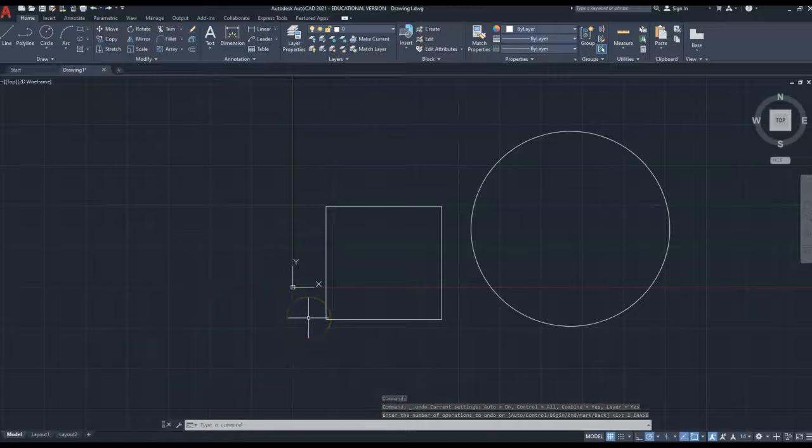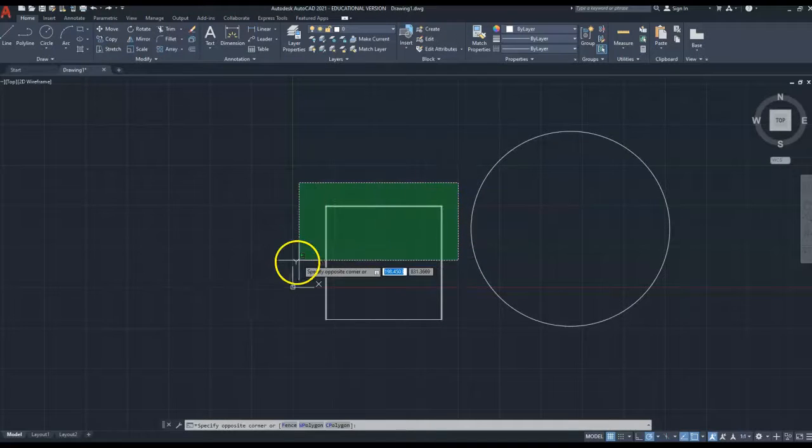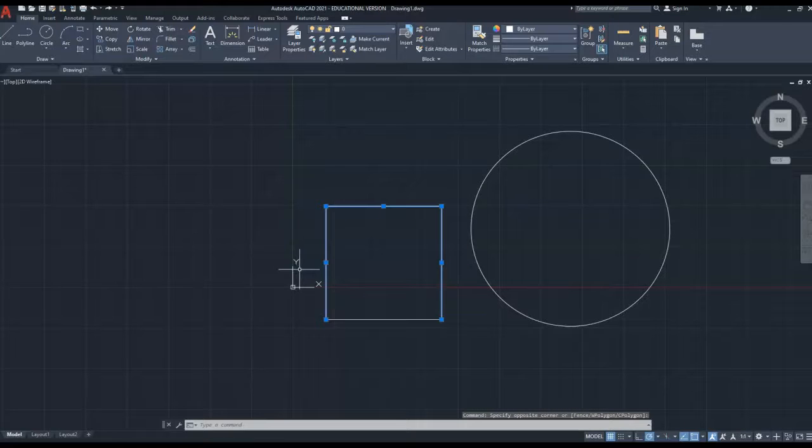Alternatively, with that blue shaded box, you've got to make sure that it envelops the object you want to take away. Now, if I wanted to lose 3 lines, I would go this side and pull down left way, and you can see now I've got a green shaded box. This means any line that falls anywhere in that shaded area, when I left click again, highlights and it will only delete those.